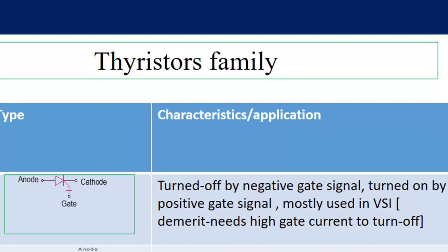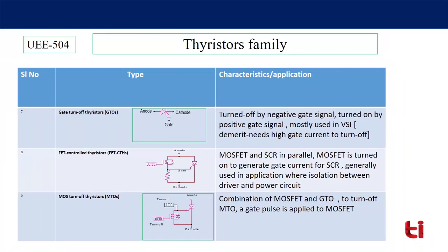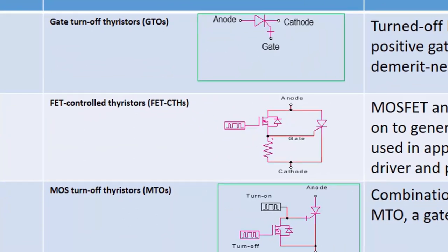Research continues to develop different types of thyristors to remove the demerits of earlier ones. Advanced thyristors are developed. Based on that, a new type of thyristor is the FET controlled thyristor, a field effect transistor based thyristor. Here a MOSFET is connected in parallel with the thyristor. Now to turn on the thyristor, we know that a minimum gate to cathode voltage is required.